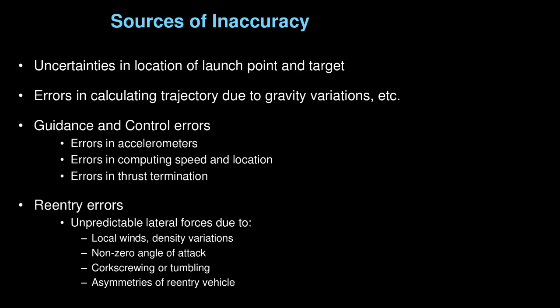the accuracy. And a particular problem with high beta warheads is that you have this ablative coating for heat shielding, and it's very difficult to have uniform ablation. It's one of the things that the United States and Russia spent a tremendous amount of time on when they were developing ablative coatings: what can you do to make this ablation occur as uniformly as possible. Because if it doesn't, then again, you're going at very high speeds, you've got asymmetric forces, and that can pull the warhead off your intended path.